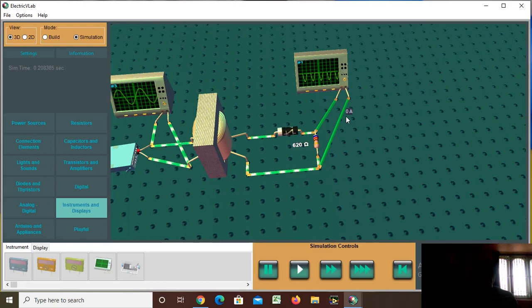You all know VDC is equal to Vm by pi for the half-wave rectifier, and VRMS will be equal to Vm by root 2. The ripple factor will be equal to square root of (IRMS by IDC) whole square minus 1. If the current is not given, you can represent that equation in terms of voltage: ripple factor will be equal to square root of (VRMS by VDC) whole square minus 1. You can use that equation also to calculate efficiency and ripple factor.